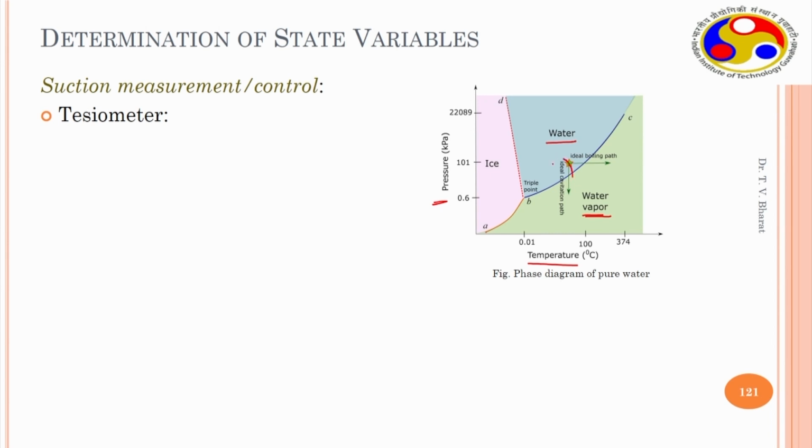We have seen that cavitation takes place when the absolute pressure decreases at the same temperature. Pardon the scaling here, this is not a linear scale, and similarly for the y axis. At the same temperature, for example at 25 degrees, when you decrease the absolute pressure of water until it reaches the vapor pressure, this is the vaporization curve. If it touches the vaporization curve, or reaches the saturated vapor pressure, then water turns to vapor.